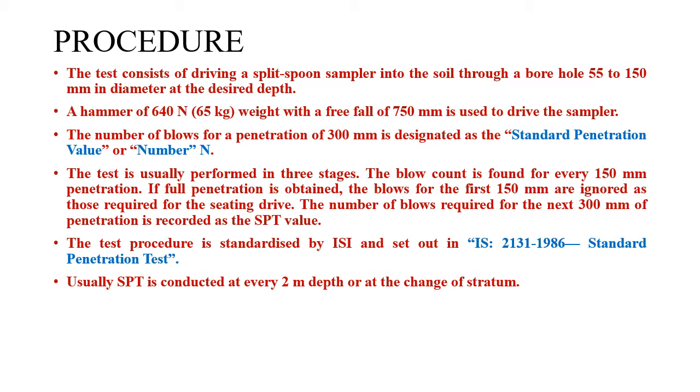Now there are certain specifications that you have to be thorough of for this test. The hammer weight which is normally used is 65 kg, or in some cases it is a 63.5 kg hammer which is used.